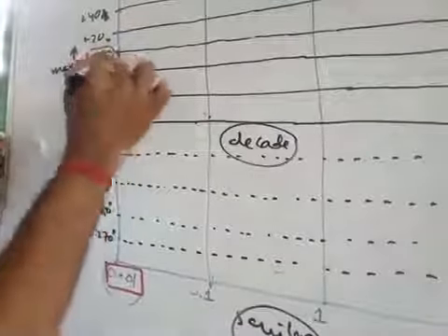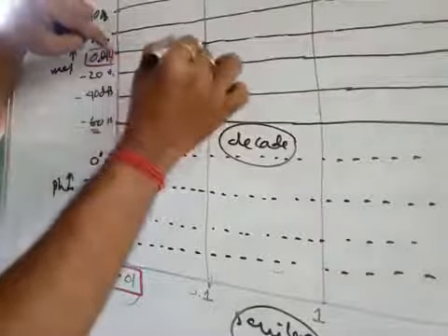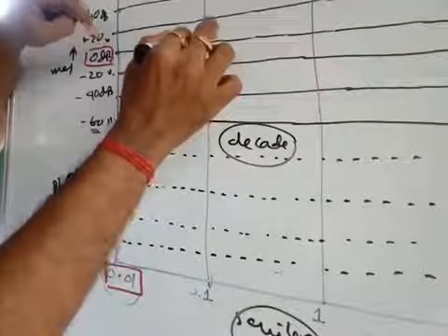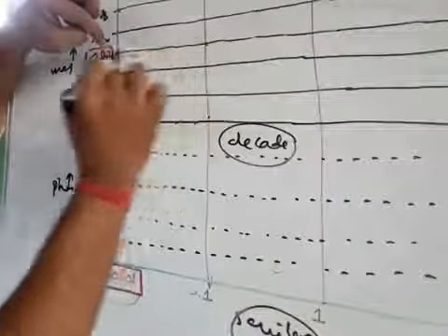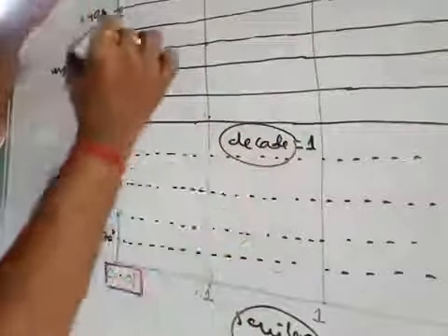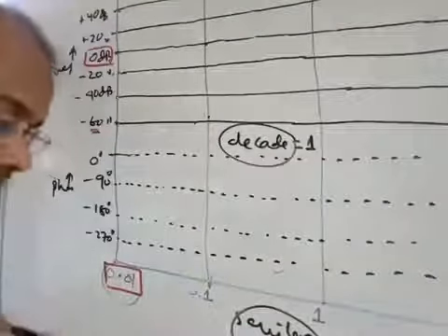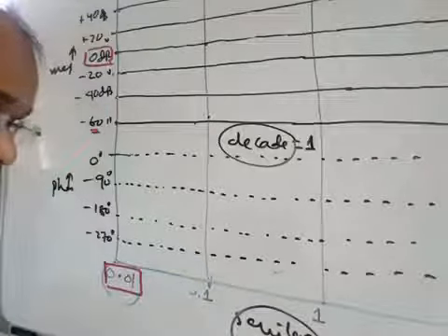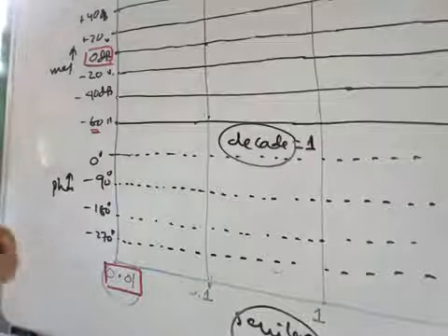So this is the frequency. This frequency to this frequency, what is the change? 10 times. That means this is known as 1 decade. 10 times means 1 decade, right? So we see how to draw the slopes, because these slopes are very important in the case of Bode plot, and I will discuss in detail later on.